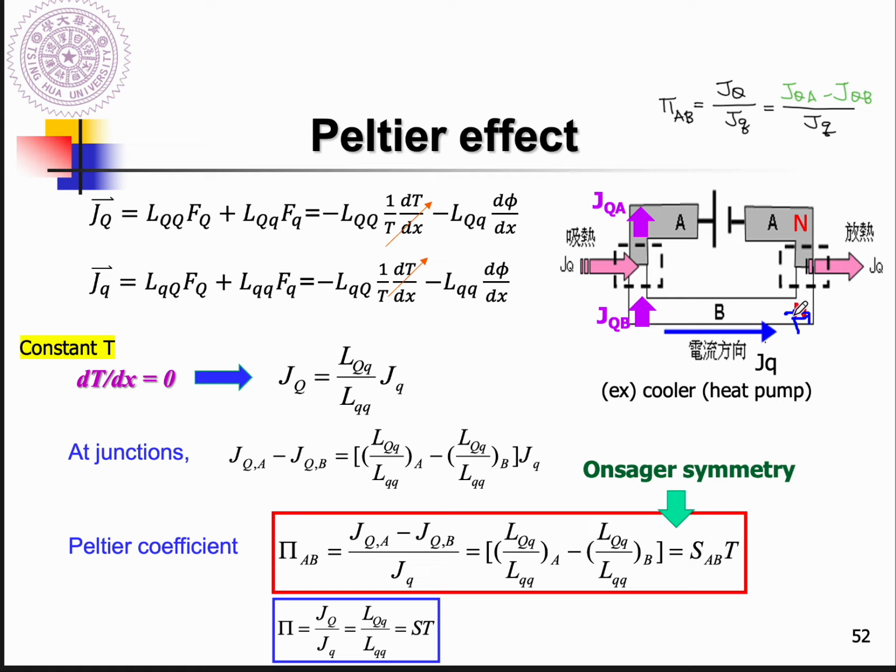Sorry, the writing is a little bit ugly. So in order to reach the maximum efficiency of the cooler made by thermoelectric materials or by the Peltier effect, NN is not a good idea, but NP can reach the maximum efficiency.